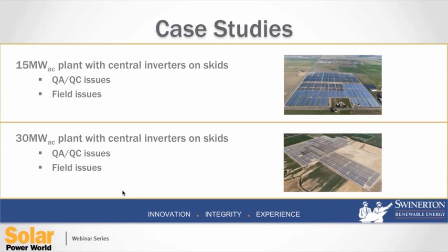It's an inverter-based monitoring system where we saw a number of QA/QC issues come up on everything but the inverter, and it helped start to frame up discussions with the integration of a medium voltage transformer or switchgear with that inverter technology. It helped create what became almost a standard, robust startup and commissioning process that included different testing, whether it be as simple as opening a breaker, a command from the utility, all the way to actual curtailment, set point testing, CAL-ISO point-to-point testing.